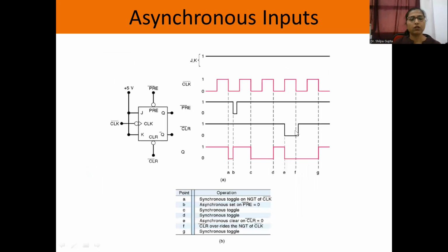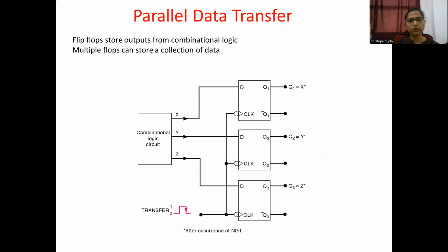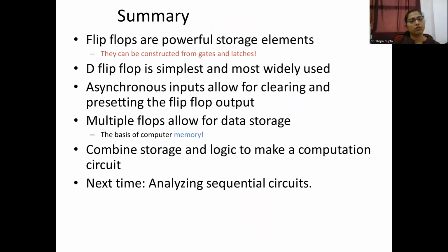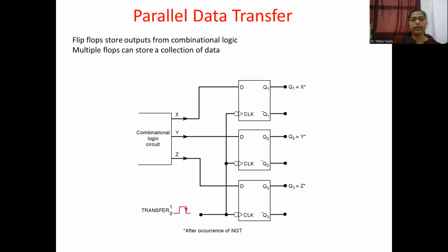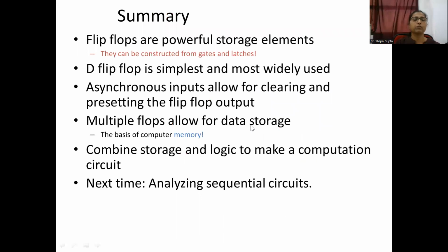So this is all about the flip-flops and the latches. These flip-flops, what we have discussed, are the synchronous flip-flops, but we can make asynchronous flip-flops when we connect cascaded flip-flops with different clocks. That becomes an asynchronous design. And when we make cascaded flip-flops and feed them with the same timing signal, it would become synchronous. So that is how we can connect the flip-flops in cascade form with the same clock. This is the synchronous design of flip-flops.